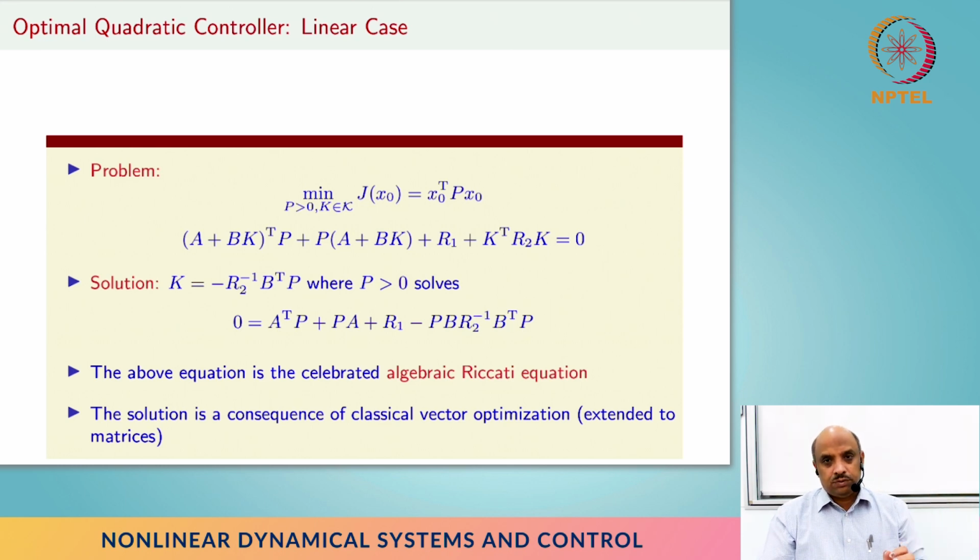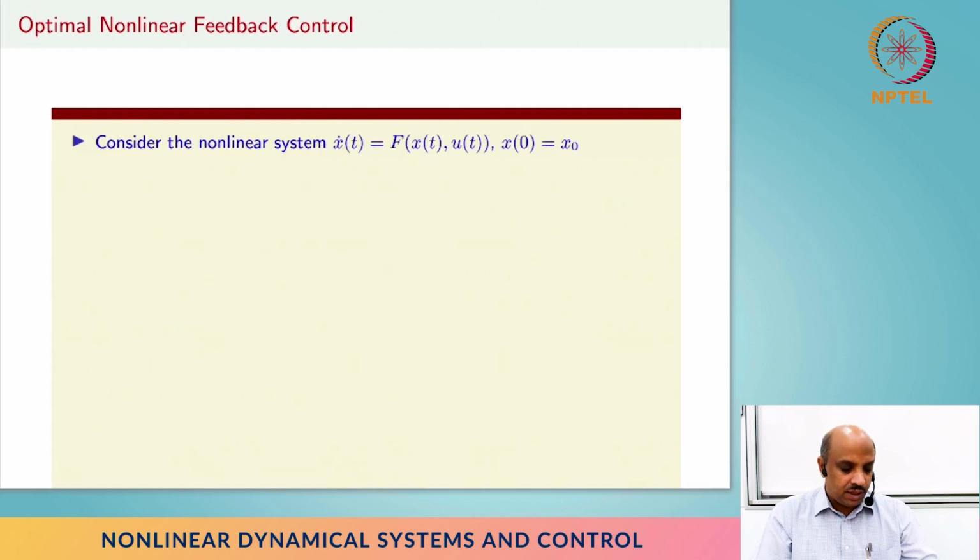So this is one of those things where you actually married the optimal control Hamiltonian type of formulation or Euler Lagrange equations to stability. So you combine these two, and then we get one single kind of framework where we solve both the problems at the same time, right? So that's the linear case. So I'm going to look at the nonlinear case, right? So in the nonlinear case, again, we will assume that x dot equals f of x comma u.